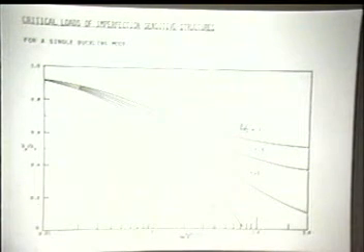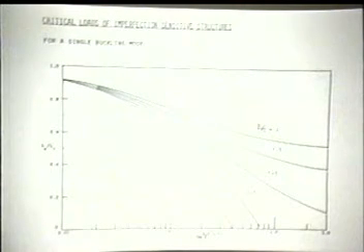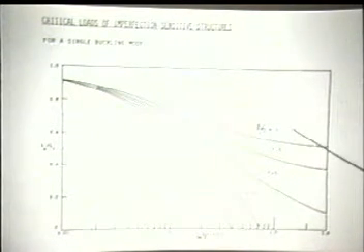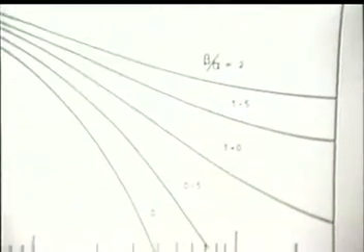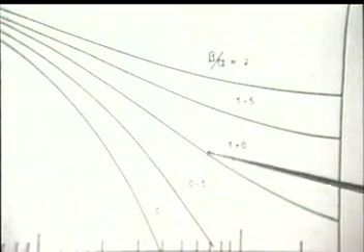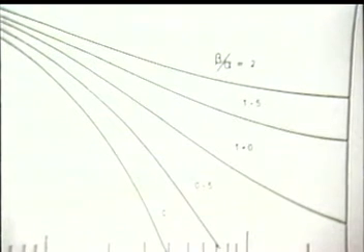That seems to better describe the physical fact that there are certain sizes of imperfections beyond which the shell will, never mind whether you change the form of the imperfection, always carry about the same amount of load. So the introduction of this beta from Jerry Cohen made it possible to extend the range of validity of this asymptotic method. Because if you don't use it, it will show here that it goes to 0, and you obviously know that's incorrect.